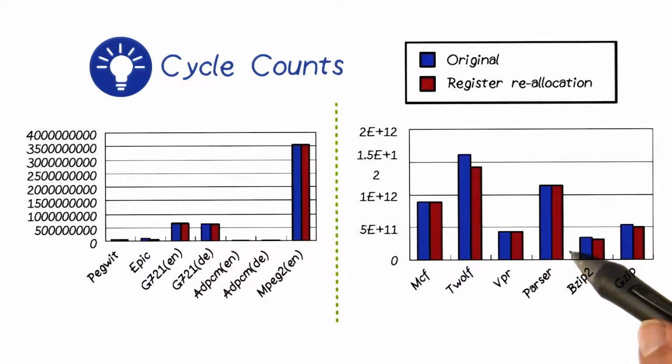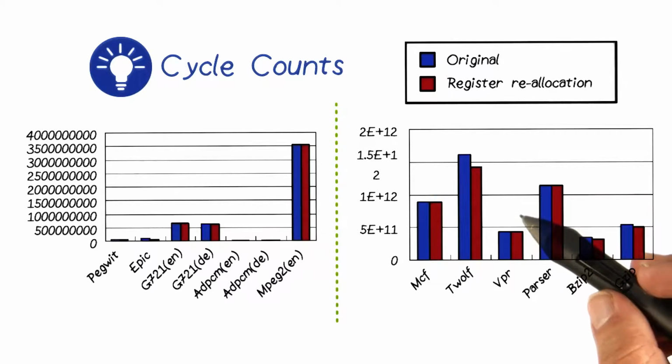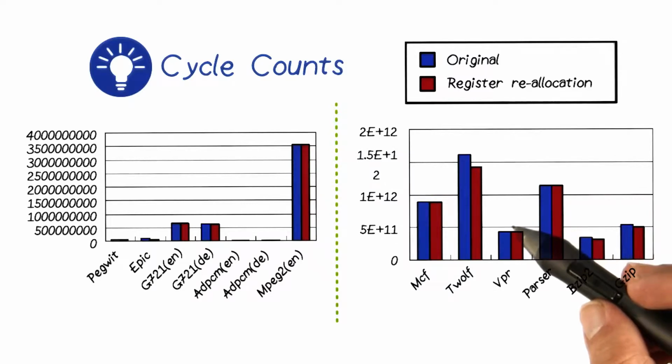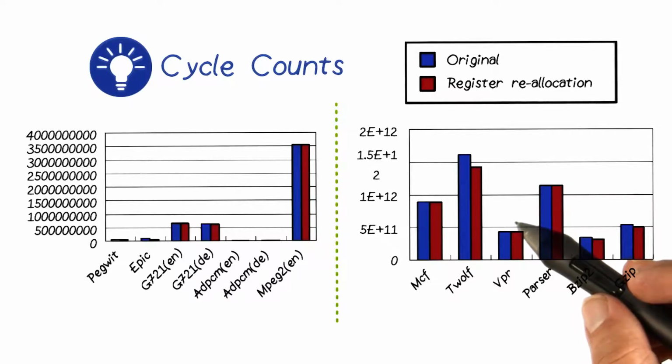Again, the main reason for this optimization was to reduce the dynamic count of load stores, but in terms of the cycle counts, or the amount of time each benchmark takes to execute, this time has not been reduced because the x86 is a dynamically pipelined architecture, and reordering of the load stores at runtime hides their latency, and so the benefits are not much in terms of reducing the latency or the cycle counts here.